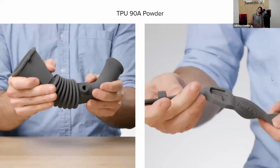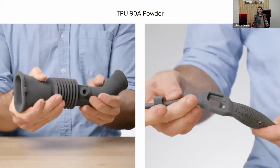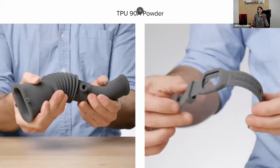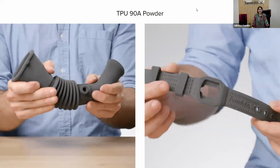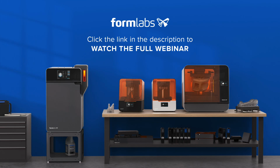And recently we also released a TPU 90A powder that is an SLS elastomer, very resilient and also skin safe. So I think this is also a great solution for a lot of different applications. It has really high elongation at break, and very good tear strength as well.